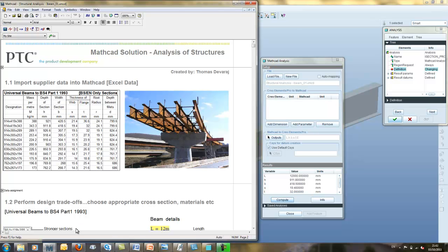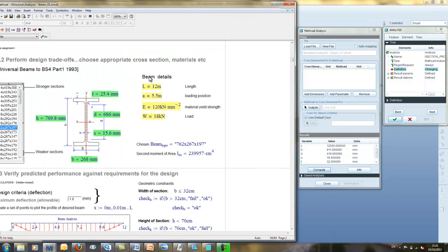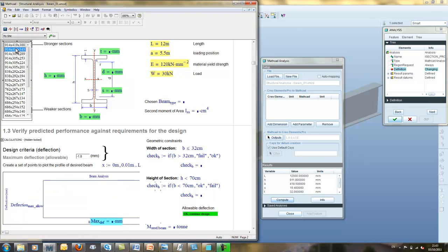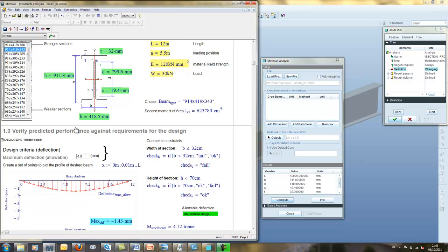This is done with an analysis feature in Creo that allows us to directly pass data to or from MathCAD to Creo. So in this MathCAD worksheet, we have a large selection of cross-sections available. The worksheet has been configured to show this as a list for quick and easy data selection. This data can be used in our calculations to understand whether our design is suitable for its intended purpose. The calculations here are referenced from Roark and Young's Handbook for Stress and Strain, provided by Knovel Solutions.